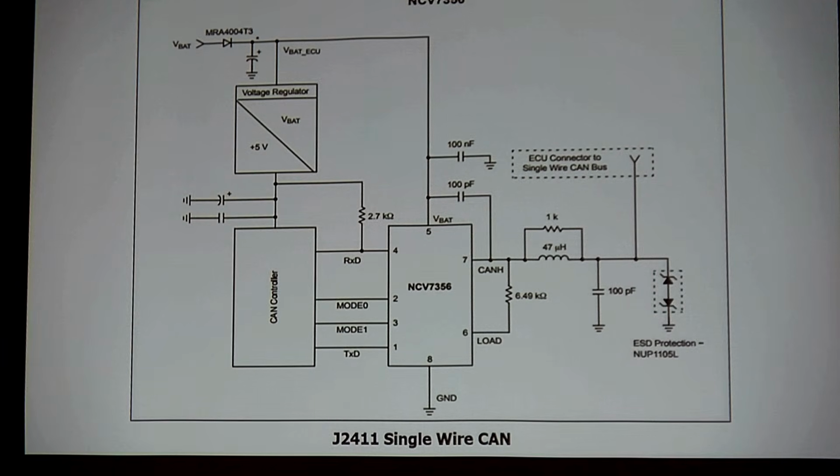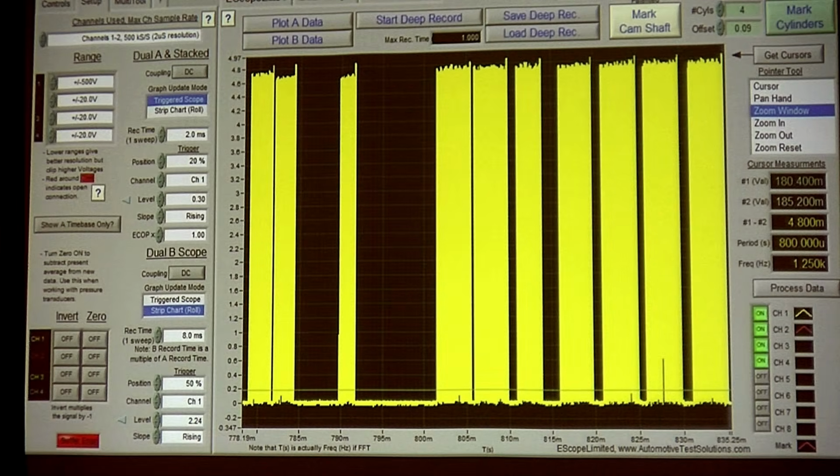So this is a single wire right here. If you see this, we have a Henry. Okay, so that's a choke. It's called a CAN choke. This can be in the systems. This is something where we limit some of the noise and some of the problems is what that's about. We don't need to get into that. This is basically what it's at. We go from 0 basically to 4.8, 5 volts. So it's a 0 to 5 volt signal. Each one of these is going to come up, and these are going to be frames of data, or packs. They are going to send a data load.